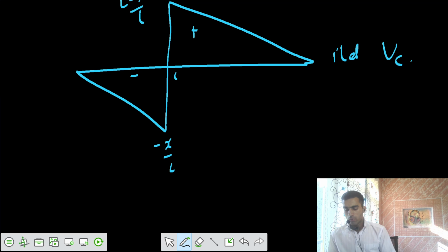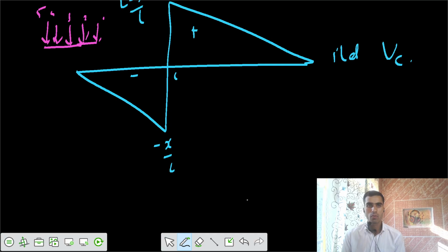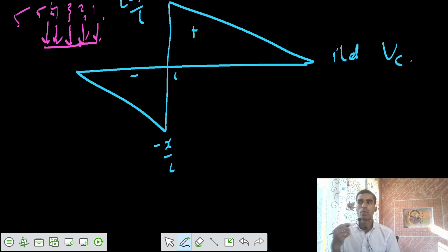Now for the negative shear force to be maximum, what can you do? There might be a number of loads with some center to center distance. Let's say we have 5 loads, 1 2 3 4 5, and we want to say where we should place the loads in order to get V negative maximum.